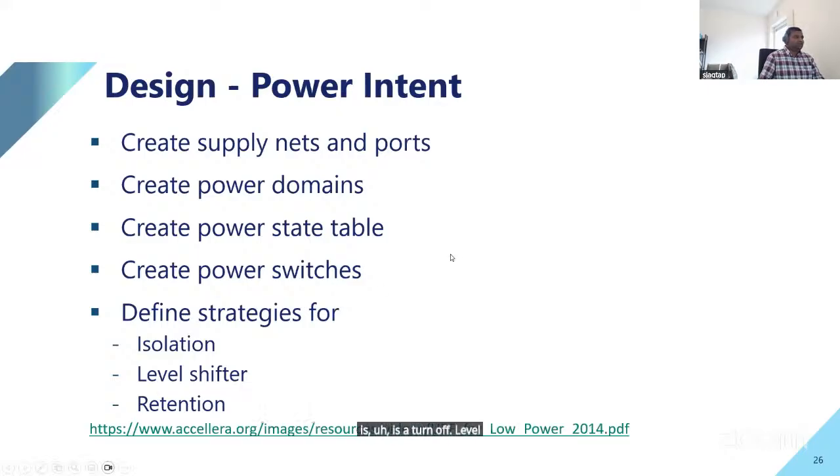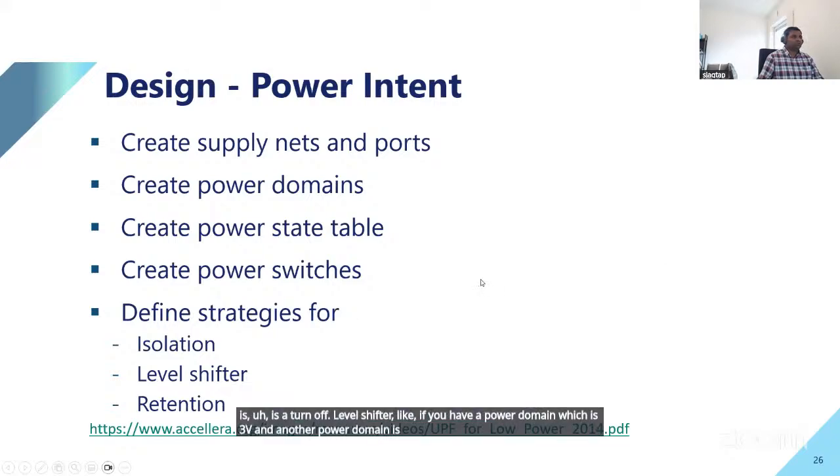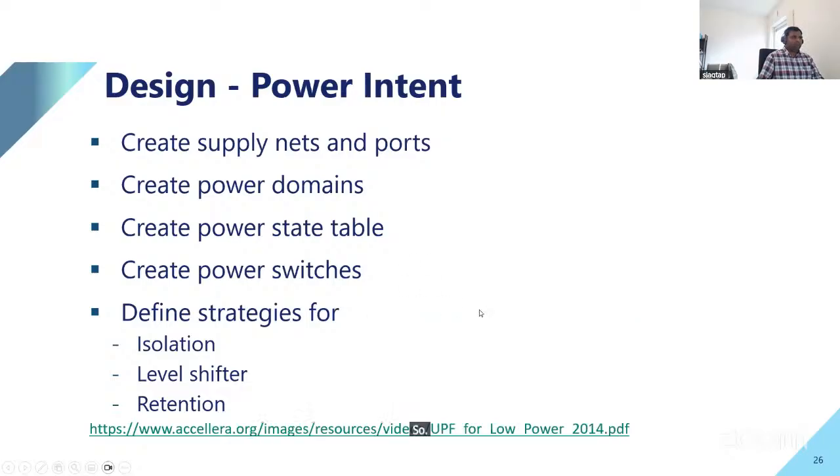Level shifter: if you have a power domain which is 3 volt and another power domain which is 1 volt, and data is moving from the 3 volt domain to the 1 volt domain, logic 1 in 3 volt is 3 volt and in 1 volt is 1 volt. So the signal should be electrically correct when it goes from the 3 volt domain to the 1 volt domain, and that's why we need level shifters. This is again industry standard.